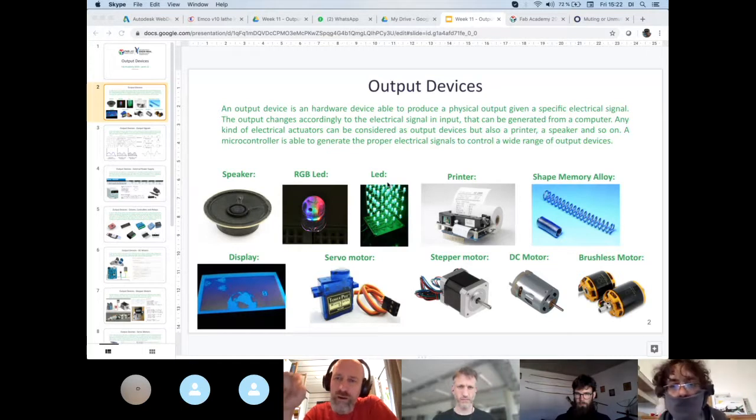My car stereo has one that goes between blue, red, and then it does purple, and other things. Is it taking one of these three-pole things and changing the relative PWM, or are there LEDs in other colors? No, it's changing the PWM for each single LED that you have inside, so each LED mixes the color. Okay. Yes, a PWM signal, and by changing this signal, you can change the color.